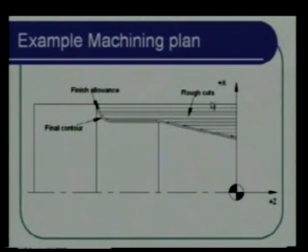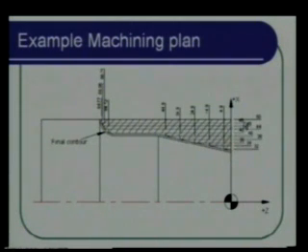I will make the lines parallel to the z-axis till they intersect with the offset contour here. And then what I am going to do is get the coordinates of all these points. You can do this manually on a drawing board, or if you have access to CAD, you will probably be better off using the CAD for the purpose of offsetting. So you get the coordinates of these, both the z and x coordinates.